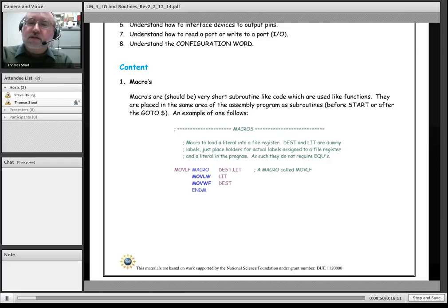Every time the macro is found within a .asm file, it's turned into the actual instructions or coding that you need. And unlike a subroutine, every place that the macro is found, it's inserted into the actual program, so it can lengthen the program significantly.